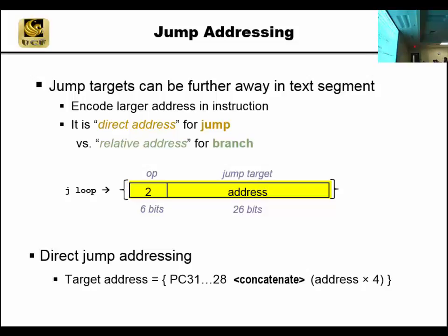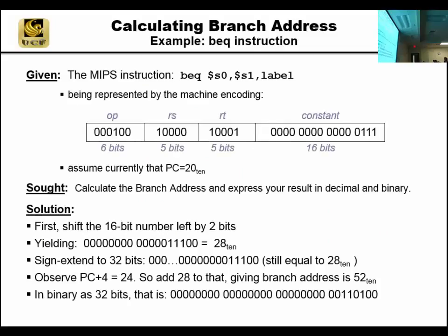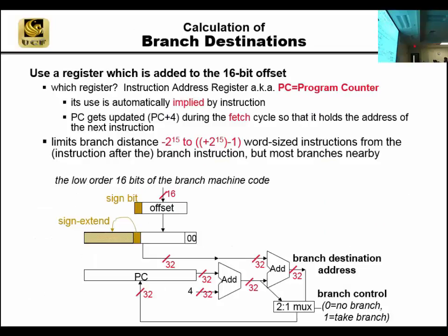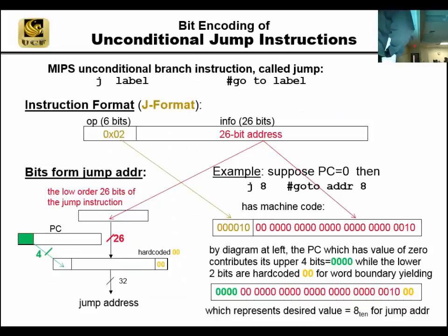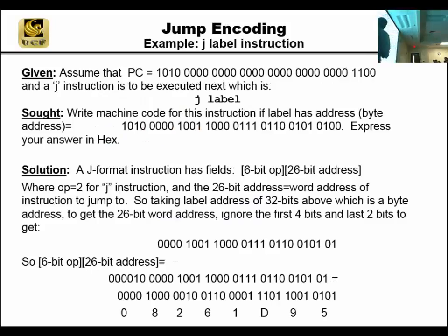But here we're looking to give the bits when we execute this instruction that the PC fetched from memory. It goes into the processor and turns circuits on and off. We're going to design more, but we're starting to see that when the bits come in, they have jobs. Some are telling us to adjust the program counter. Some will actually change control signals, turning on and off elements of the data path. So we're asking you to write those bits for that particular instruction.